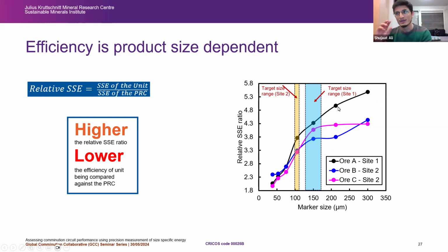So one important thing to remember is that if you have a desired particle size range, the optimal approach is always to create a narrow size distribution within that range. I know it's hard with the current technology, especially milling technology, because you do not have any control over your grinding environment. But it also gives us an insight that we need to look into modern ways of breaking rocks.